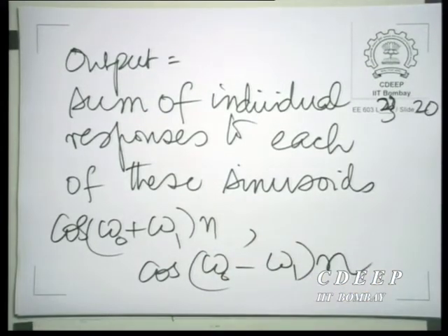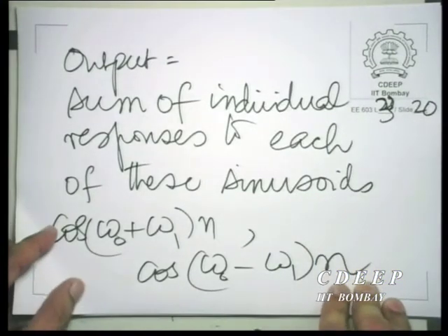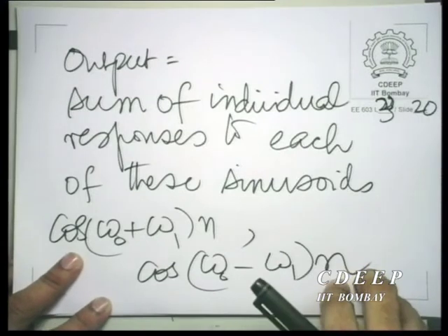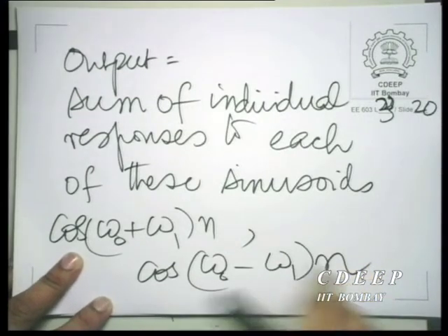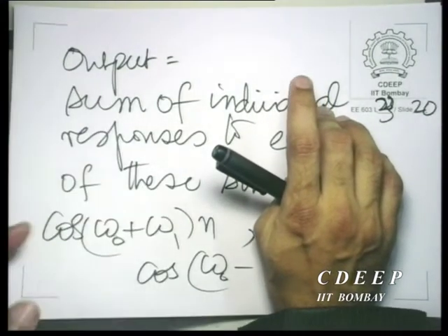You are guaranteed that they lie within the band in which the frequency response is specified. Again, I must stress that you do not need to worry about the frequency response on the negative side of omega, because it is conjugate symmetric. That is given, since the impulse response is real.